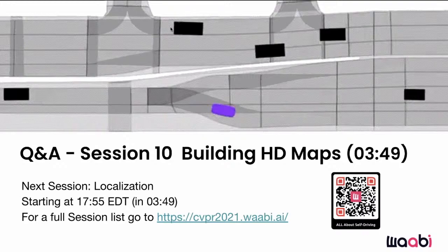A lot of the HD map annotation is actually done more or less from scratch, which means that you don't necessarily need perfect alignment with, say, OpenStreetMap or something. And in terms of just pure routing, even if you're just routing basically, oh, turn left here, turn right here, then a coarser alignment within like 1 or 2 meters is enough in that case. And then for the annotation, you annotate on your reference frame for exact lanes, and there you have guaranteed alignment because you just built the map.